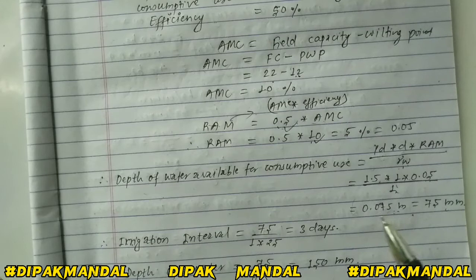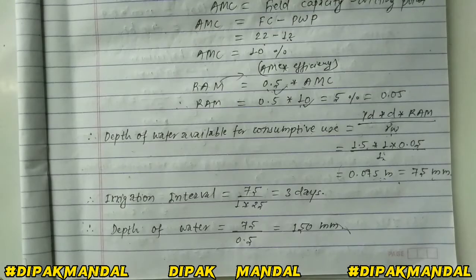Now we can calculate the irrigation interval, equal to this depth of water available, 75 mm, divided by the consumptive use. So the value of irrigation interval becomes 3 days.